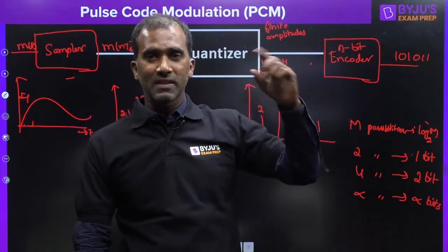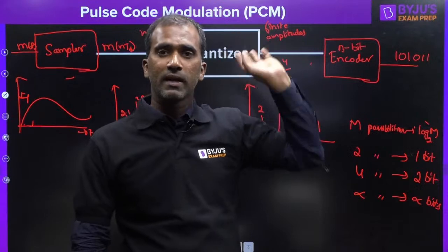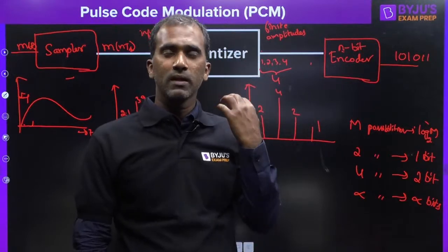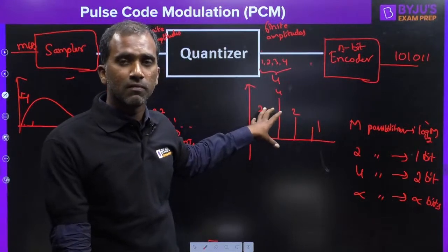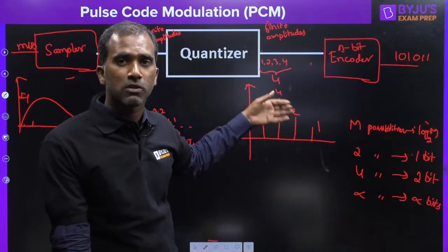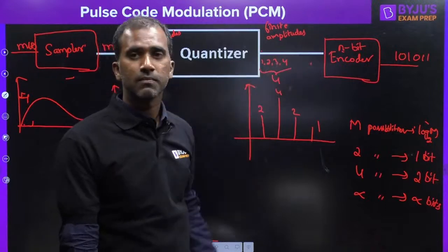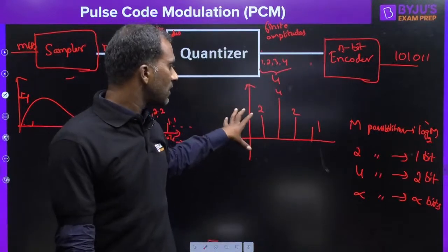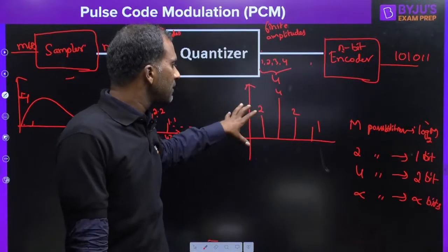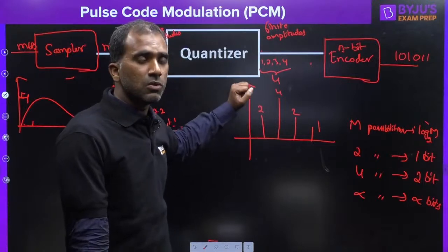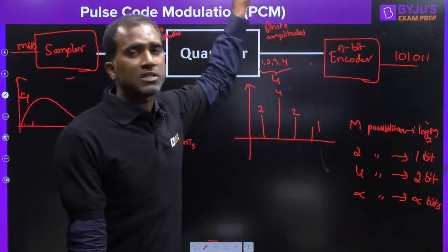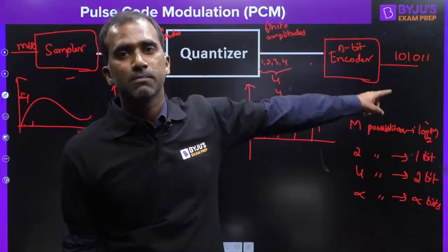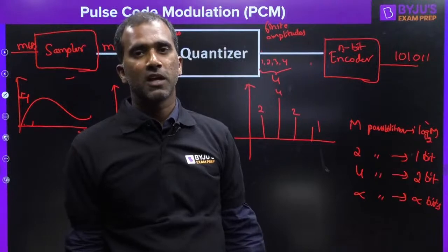If n is less, more quantization error will be there, and quality gets impacted. With more n, the quality reduction because of quantization error will be very less. But just to get superb quality, if you try to increase n too much, that will increase bit rate or bandwidth, which we can't afford.